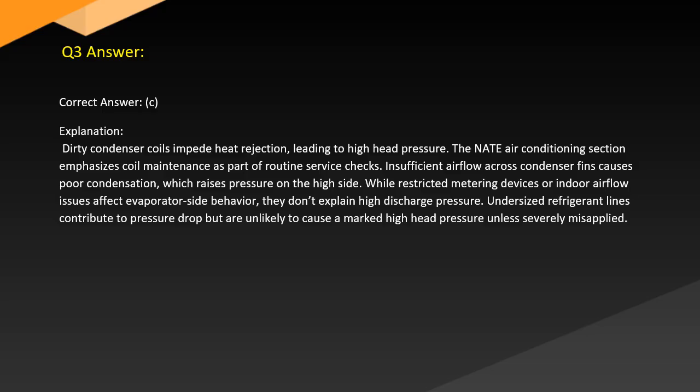Answer. Correct answer, C. Explanation. Dirty condenser coils impede heat rejection, leading to high head pressure. The NATE air conditioning section emphasizes coil maintenance as part of routine service checks.